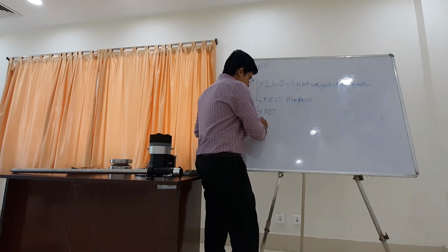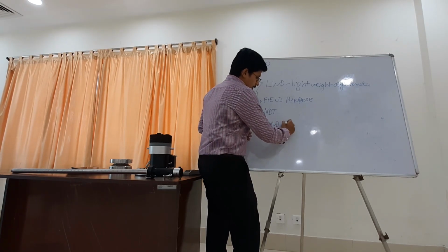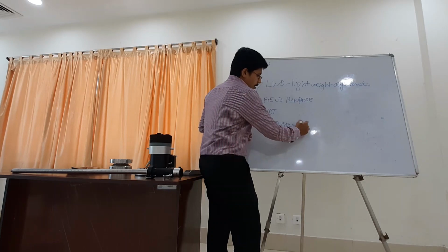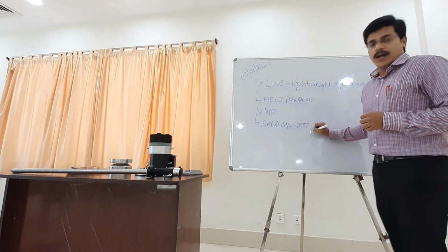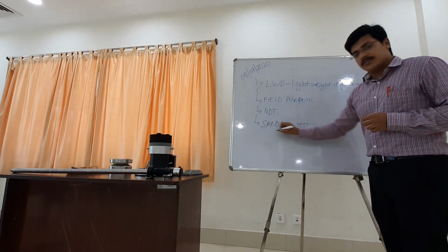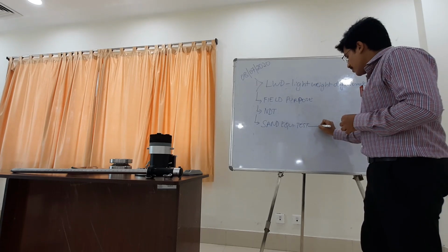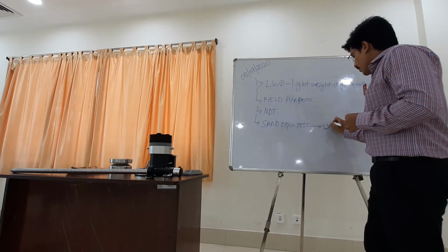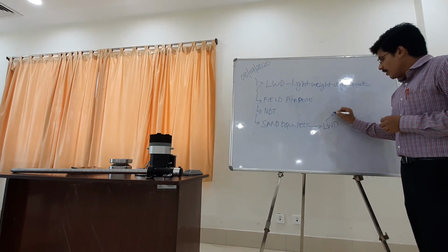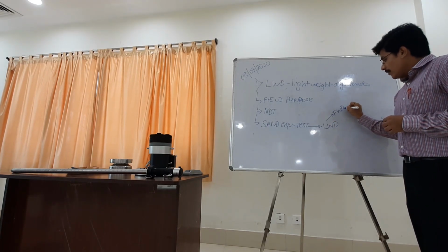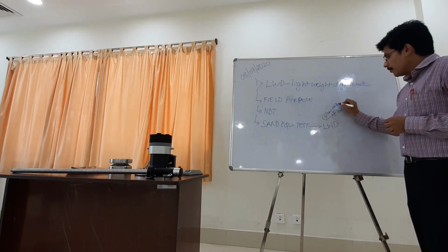In that case, normally we do sand equivalent test. But this is more laborious and time consuming. And also it will create a lot of holes in the subgrade soil granular layer. To avoid this, we use a non-destructive method called LWD. So LWD is similar to FWD what is in the class. Similar to FWD, but at a low impact load, low impulse load.